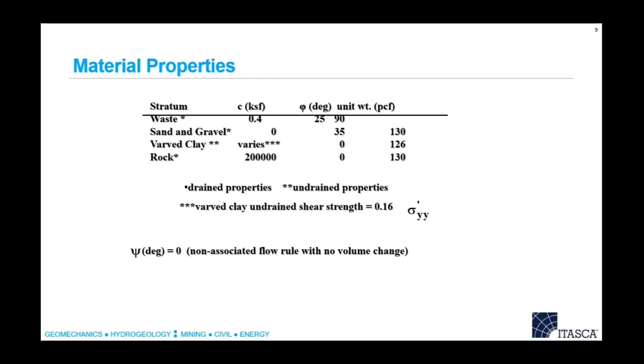If you're not used to it, it's like temperatures. If you're not used to thinking in Celsius, you just don't have an intuitive feel for it. So often what our own people do in our office is they'll do everything in metric. And then if they need to show the clients, they'll put the values of stress or displacement or whatever as extra variables and then show that in the plots, right? So you take your displacement in meters, multiply by 3.3, store it as an extra variable, and then plot that and say, here's my displacement in feet. And that's what we do all the time.